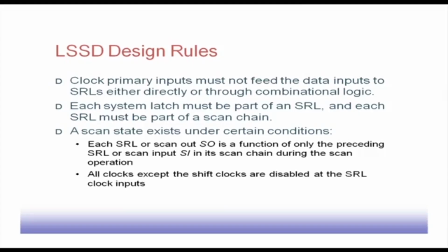Or if it is through combinational logic, say with some logic operation around the clock and then applied to the SRL data input, then also the same problem occurs: when the clock is active, the data input may flicker. So, as a result, the operation may be problematic.